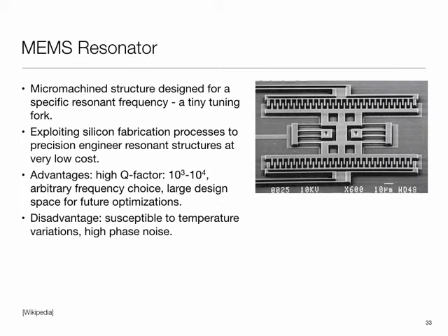There are a whole bunch of other cuts also. MEMS resonators, that's something new which has emerged over the past 4 or 5 years. These are seeking to create mechanical structures on chip in silicon which oscillate at a particular resonant frequency, and are trying to achieve quartz crystal type performance. Their intrinsic performance is not as good, but by putting in some fancy signal processing, they're able to achieve very good performance, very high stabilities, comparable to crystal oscillators.